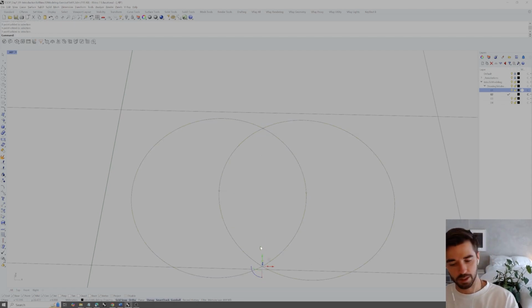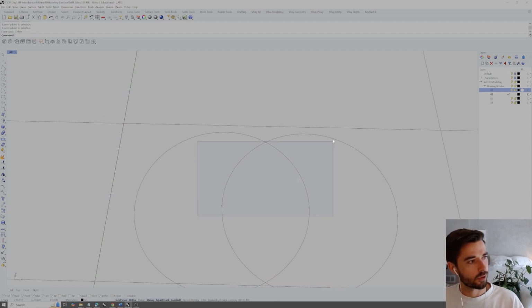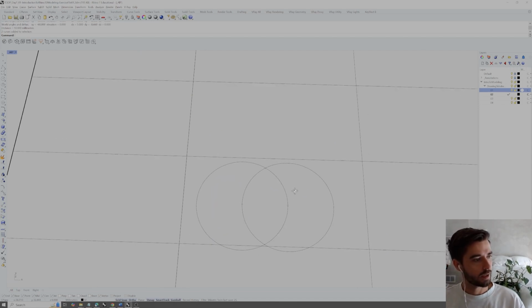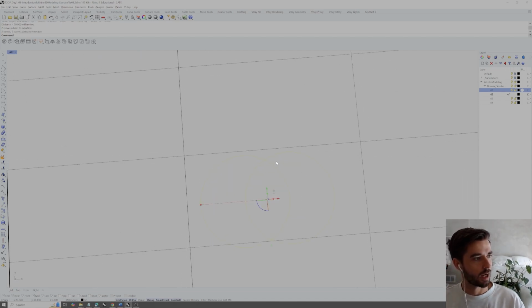So all we need is 1. We'll just use the top one here. And this is going to give us our 3 base points. So just to double check, if I type distance, I can double check that this is 10 millimeters. So the first 2 points are 10 millimeters away from each other. And if we check that second point, that's also 10 millimeters from the first and 10 millimeters from the second, which is exactly what we want. Okay, so once we have that, what I'm going to do is just go ahead and copy all of these up to the next step.